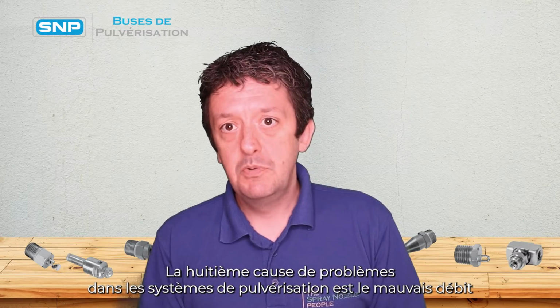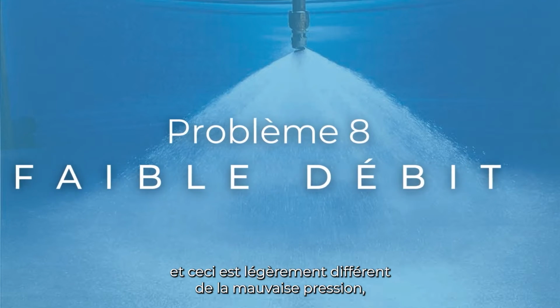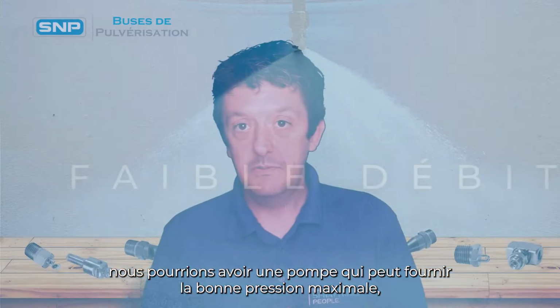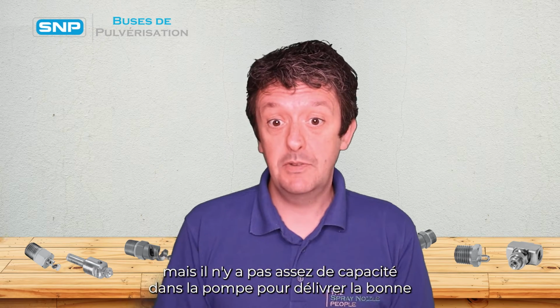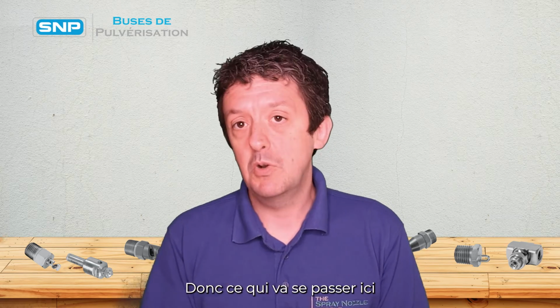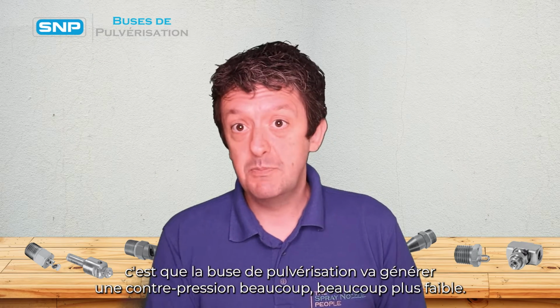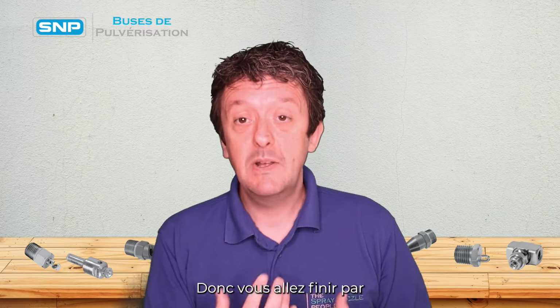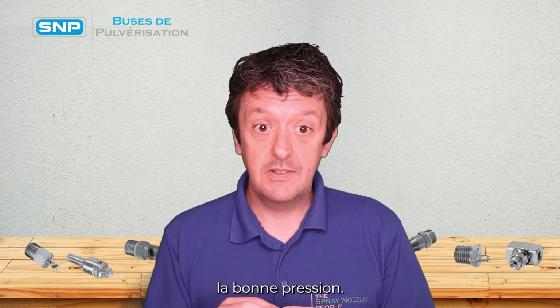The eighth cause of problems in spray systems is poor flow rate, and this is slightly different from poor pressure. We could have a pump that can deliver the correct maximum pressure, but it hasn't got enough capacity to deliver the correct flow rate. So what will happen there is that the spray nozzle will generate a much, much lower back pressure. So you're going to end up with similar types of problem to having a pump that cannot deliver the correct pressure.